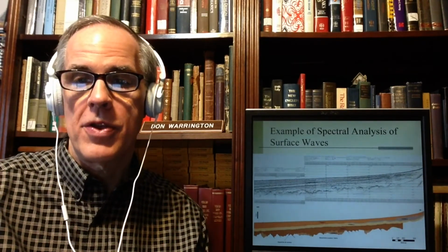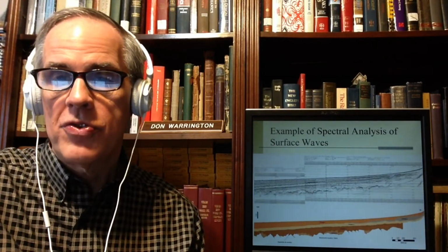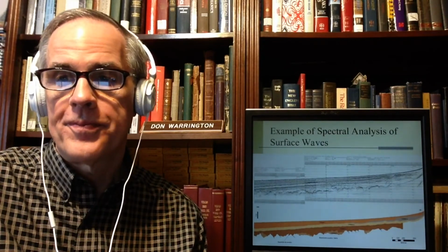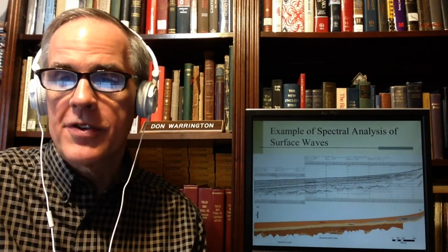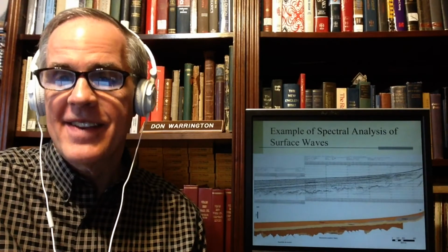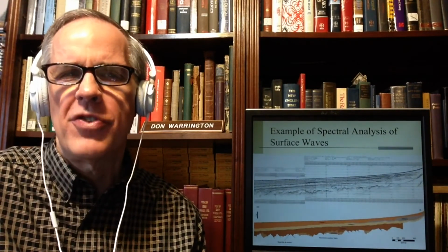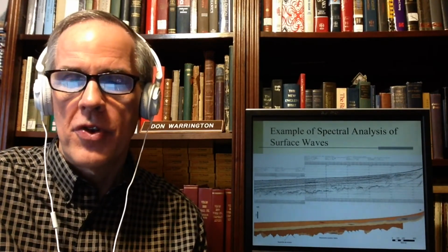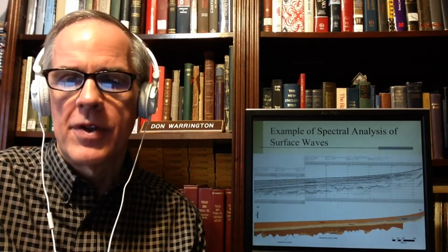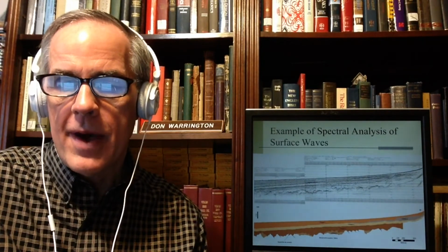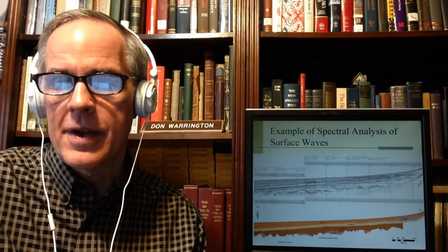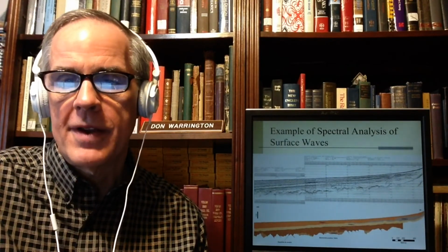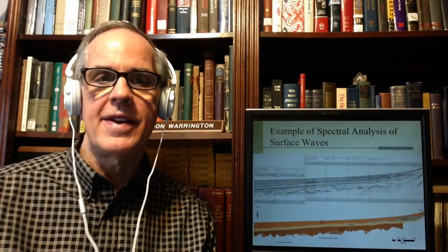And this is from Colombia. You see at the top, they took seismic refraction, and with more modern instrumentation, they developed a decent looking profile of what the soil looked like. And then they took some other borings and put together what they had at the bottom, which is a more detailed profile of it.